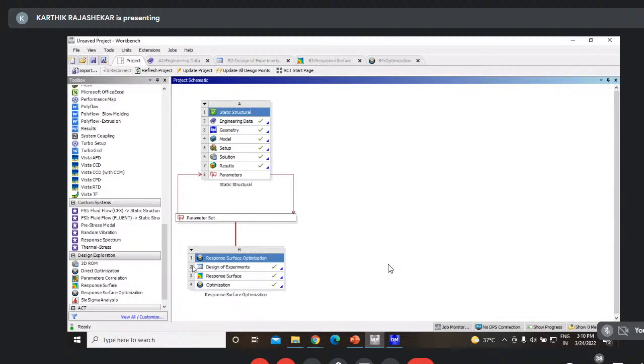So wherever you have a large amount of stress, if you increase the thickness, definitely the stresses would reduce. Wherever there is no stress at all, there you can remove a certain amount of material, because adding more material increases the weight of the component. Indirectly, it is not good for any kind of automobile component. So for that reason, you can also go for topology optimization. I'll just explain with a basic example how to do the topology optimization.